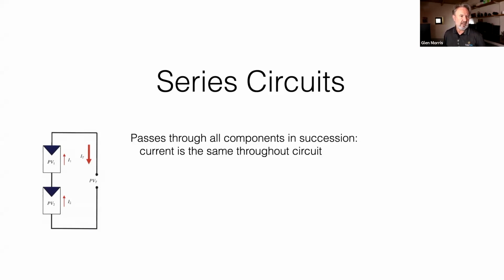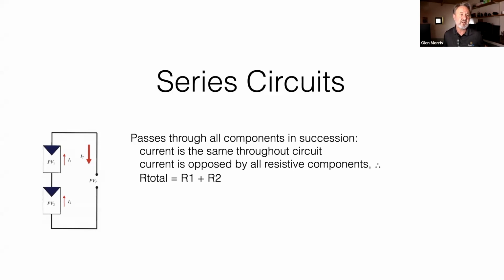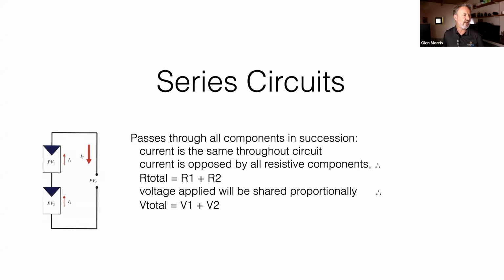There's a little example here. And if you're looking at resistance paths within a circuit for impedance, you can do the same sums as well. So in many ways, a solar panel follows the same rules that resistive circuits do in terms of parallel and series. So voltage is summed in series, and the current stays the same as one module. Now let's contrast that with